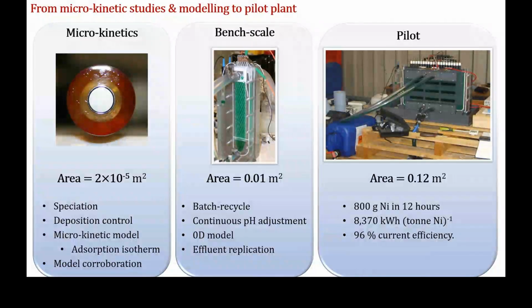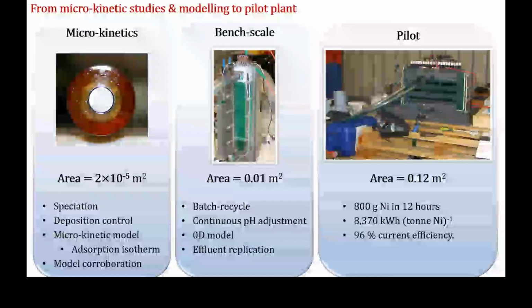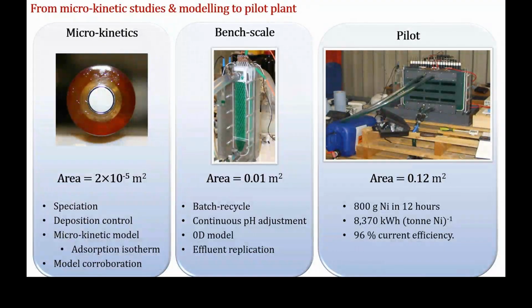And so just in a nutshell, my PhD project involved, first of all, getting samples of the effluent from the Royal Mint, but of course, that contained all kinds of stuff besides nickel. It contained iron, it contained rust, and all the other stuff that might end up in wastewater. So what we did is we simulated the wastewater by making quite a pure solution. So we bought some nice pure nickel sulfamate salts, and we made our own plating bath, and we studied how nickel electrodeposition actually works. And we did this on a small scale, starting from thermodynamics and microkinetic investigations.